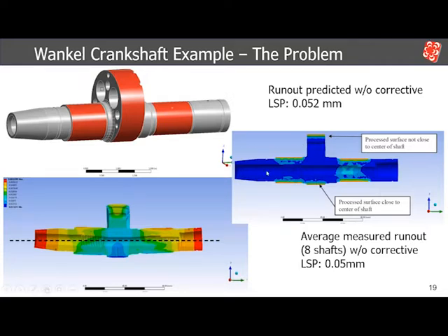And so if we look at what laser peening does to this type of geometry within our internal structure, with a cross-sectional view of this crankshaft, our issue comes in where our residual stresses, or our misfit strain, are distributed unevenly around the center line of the crankshaft because of this eccentric lobe. What this does is create an upwards curvature in the shaft, and ultimately we have a runout of 50 microns on this crankshaft. In order for this to be acceptable to run inside an engine, this value needs to be below 10 microns of runout.